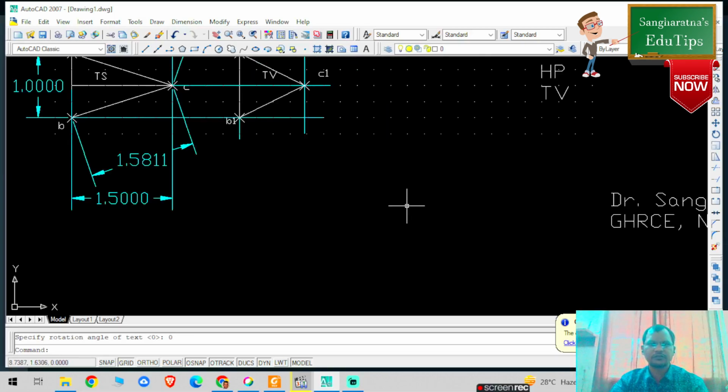So what you need to do, you need to draw one projector from this A1 B1, right? And you have to draw another reference line X dash Y dash, or X1 Y1, having an inclination of 45 degrees to this particular base, right? And then you need to project again the line perpendicular to XY, right?